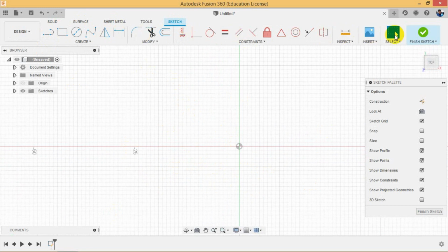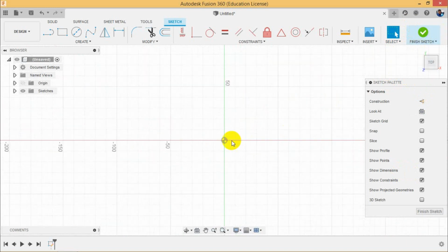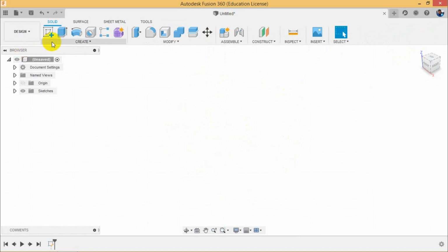You can see the sketch commands in here, and there is a sketch palette. Notice that immediately after selecting the top plane, I am in this top plane mode. But some of you may face this in another way. You may face this like 3D mode. Still in the 3D mode, you are not going to see this perpendicularly, looking at this top plane. So that's a problem. How you can solve that problem, I'm going to show you that. I'm escaping. You go to the preference.